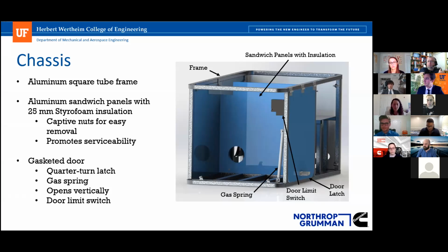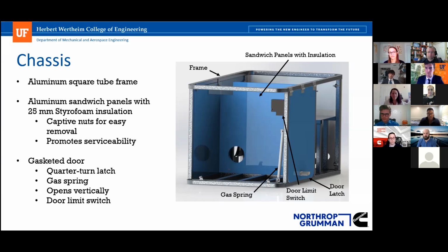So if that's sitting at 70 degrees C, what temperature is the outside surface of that box beam at? Yeah, we've run these calculations, and it barely gets above 25 in almost all situations. The inch-thick styrofoam pretty much hinders any kind of heat transfer through there.